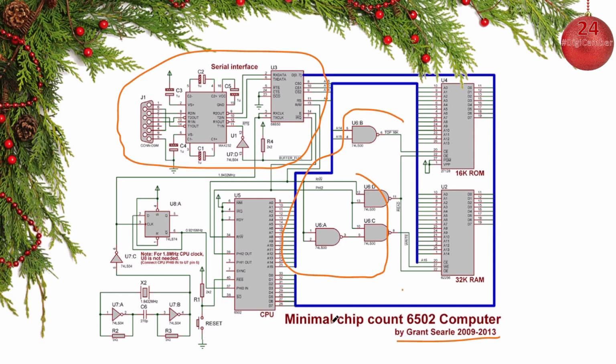So this is also a very simplified design, and in all its simplicity, I think it's rather genius. But he has done some mumbo jumbo with the clocks here, as you can see, and that's probably because of the UART and some timing issues. Because you don't need all this clock to make things work.